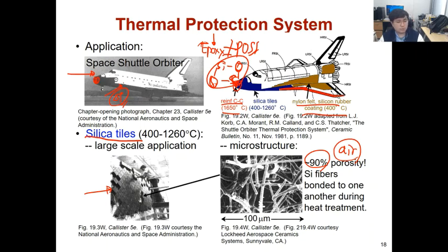Solid material has a much higher conductivity. Although we say a polymer has poor thermal conductivity, compared to gas or liquid phases, the conductivity of solid material shows a very high value. So to reduce the thermal conductivity of the solid material, we must contain very large void spaces.